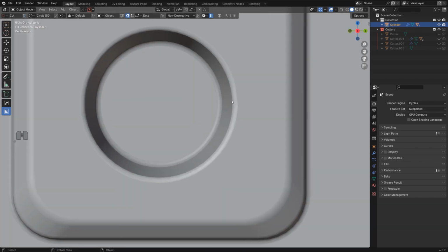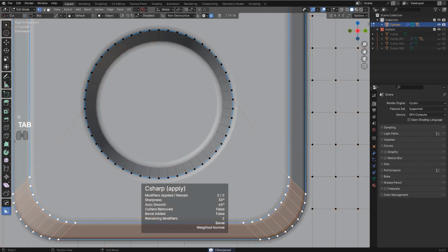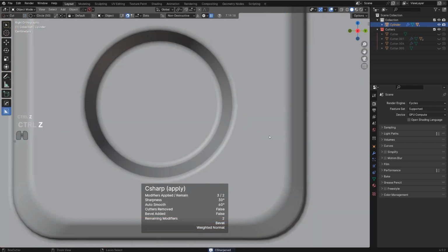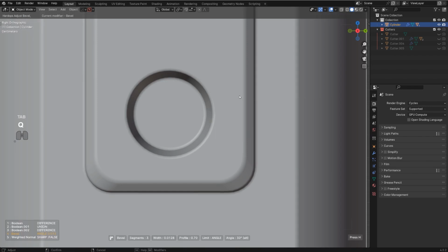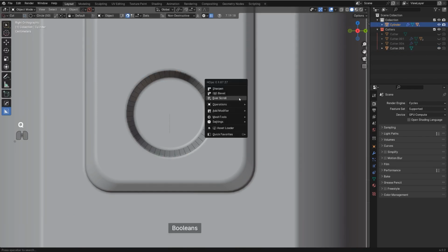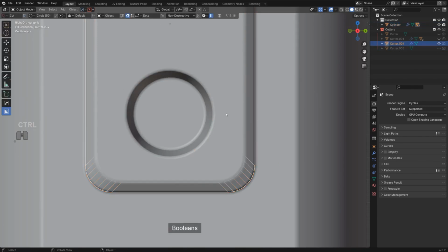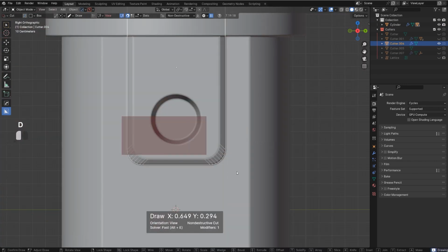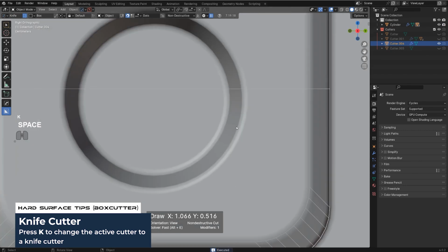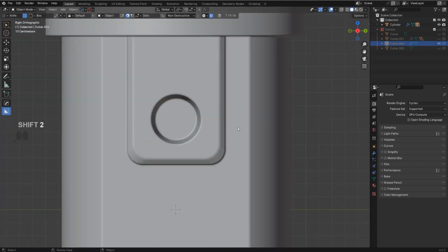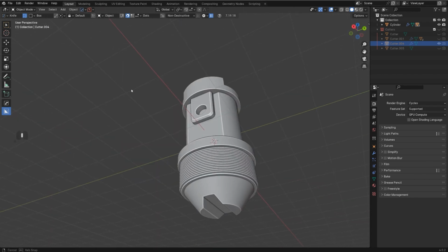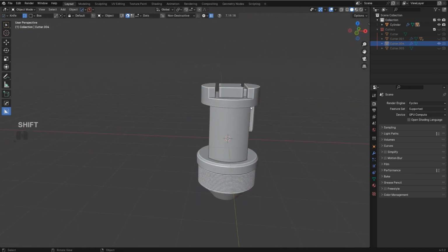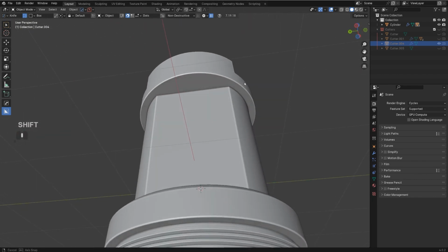Now we got some problem with connections here. I can see that in this one. When I apply this, you'll see what I mean? It goes so steeply. Let me recover this cutter here. Not this one, this one. And let's just run a loop here like this. So go to cutter, cut it, K and knife, and it's going to fix this problem here because now we got a cut coming through the circle. Blender has this weird condition of connecting edges in the worst possible way.